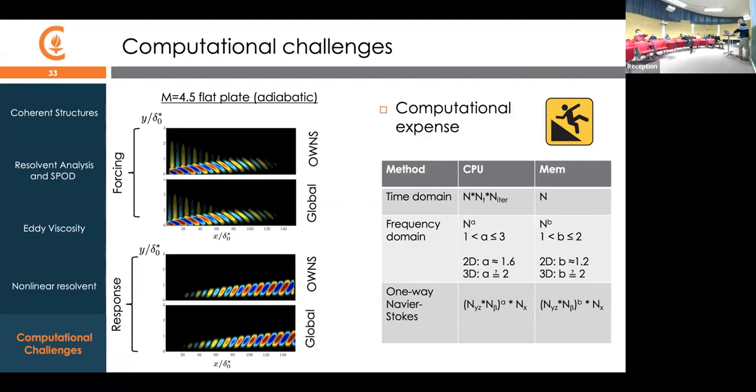Yes. I have a second question. Now I'm a mathematician. I would like to be a little bit more, I wouldn't say completely rigorous, but semi-rigorous. Now I have an equation like the Navier-Stokes equations. You take the most energetic modes, so they are optimal in some energy norm, but the equations involve gradients, involve the Laplacian, and if you are optimal in the L2 norm, you need not be optimal in the gradient norm or in the Laplacian norm. So why should I think that truncating, or ignoring the Laplacian of the higher coherent structure modes, is small? We have a physical argument for that, but mathematically I cannot see it.